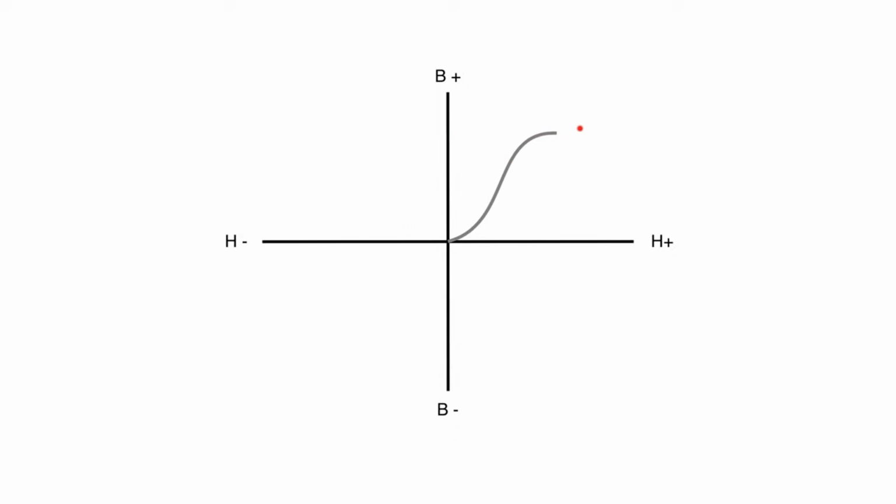And that point is called our point of saturation, which means that no matter how much magnetizing force you put on this, if we keep increasing it, you can't put any more flux lines into that piece of metal. It's like putting toothpicks into the little toothpick bottle: it gets to a point where it's all full. And so we hit saturation. So we're going to see what happens when we do that. We magnetize it, and then if we get rid of our magnetizing force, let's see what happens.